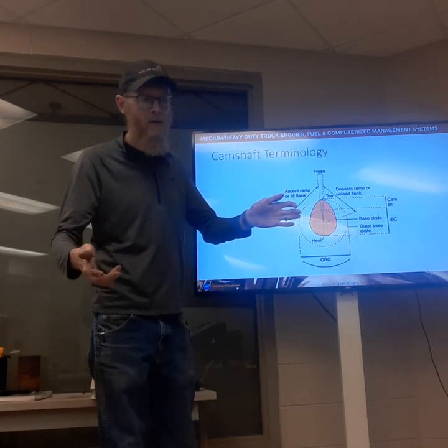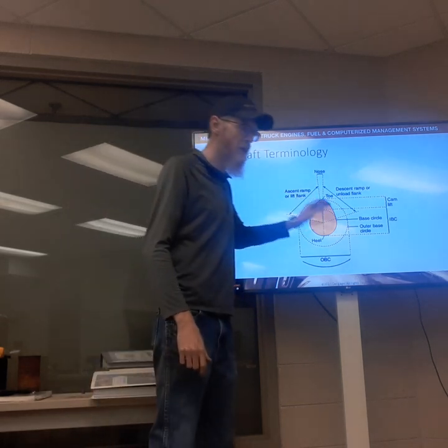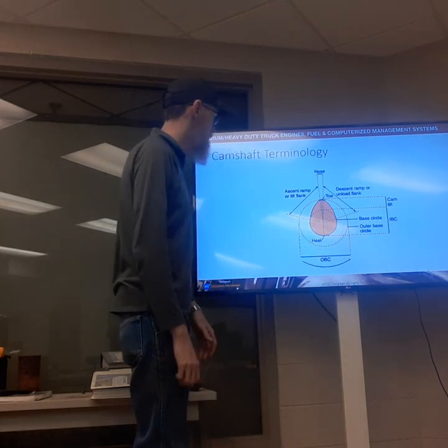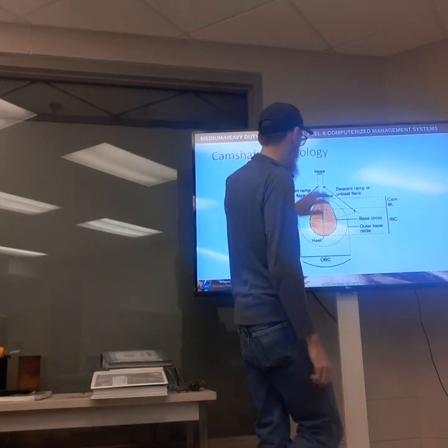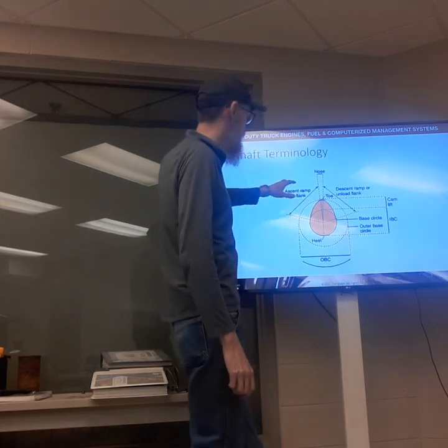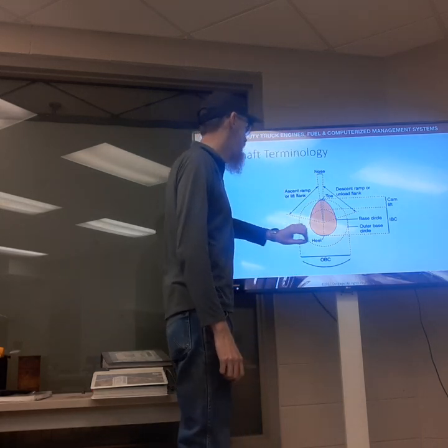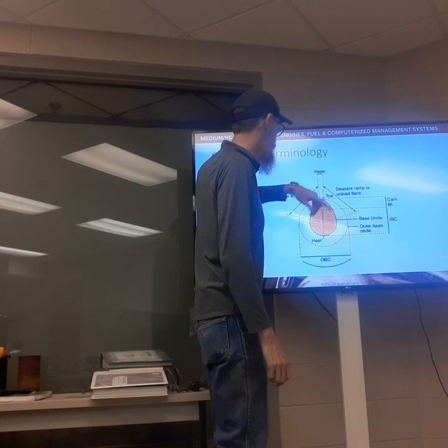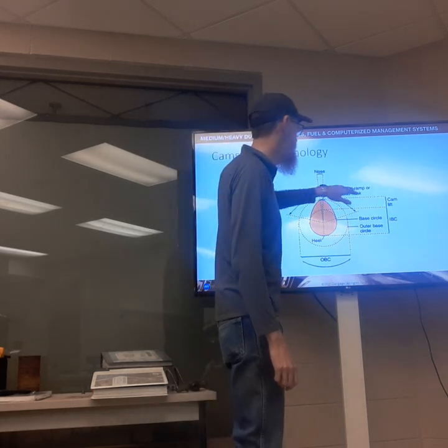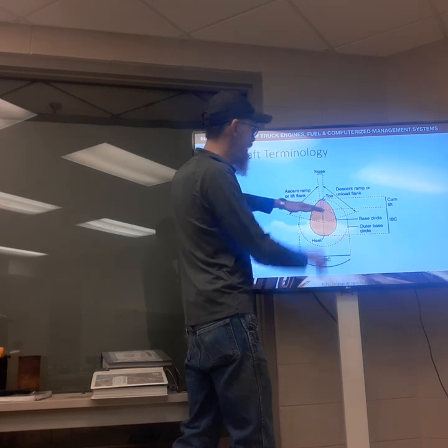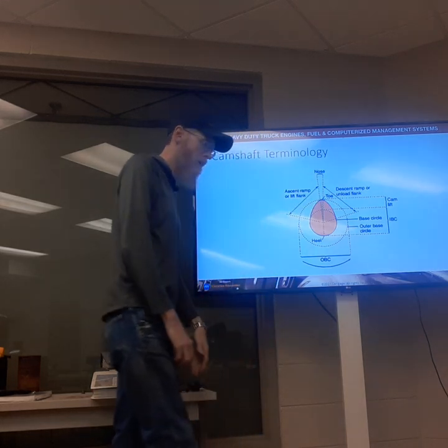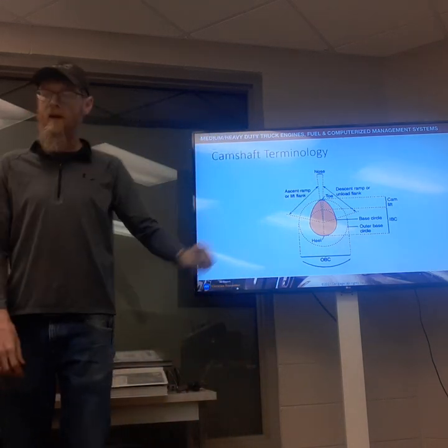Or if we're talking about the injector, it's when the injector is not being fired. The next part of the cam lobe geometry that is quite important is the nose, or the ascent or descent ramp. And that's where we're going to get our linear movement for the opening and closing of the valve.